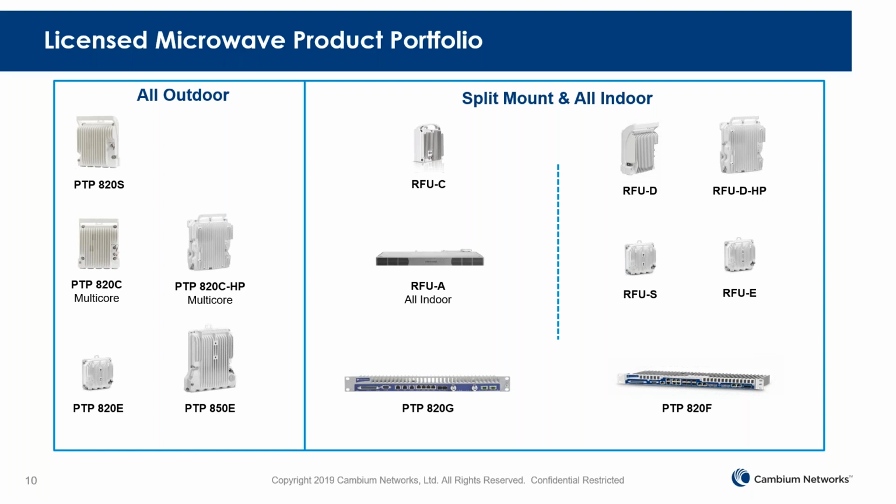Most are on the 670 line. The radio on the DSO mode, the dynamic spectrum optimization. This is basically the radio scans the whole spectrum, and the radio always works on the lowest interference channel. So when you have that, the radio will search the channel itself. You kind of like let it go.